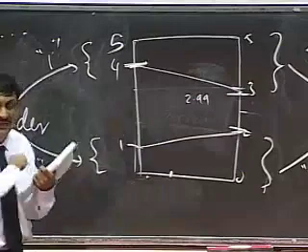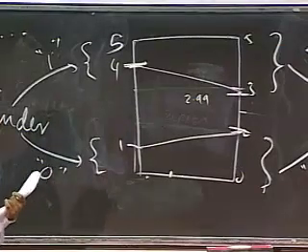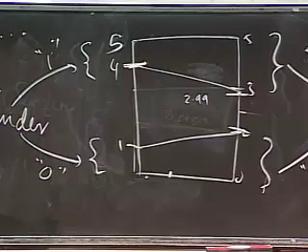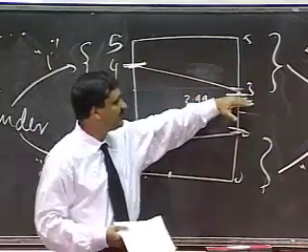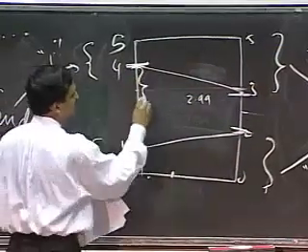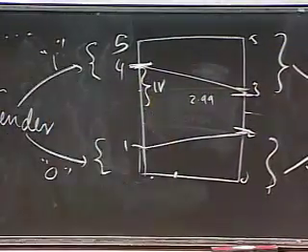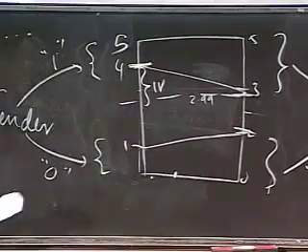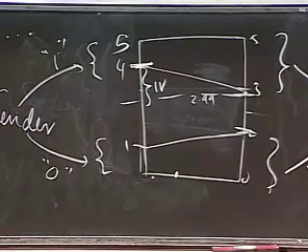So if I sent a 4 over a long cable to you, the value can be beaten up by noise to such an extent that you may begin receiving 3s, but nothing lower than a 3. So this is a noise margin, 1 volt. Similarly, for a 0, the noise margin is also 1 volt.